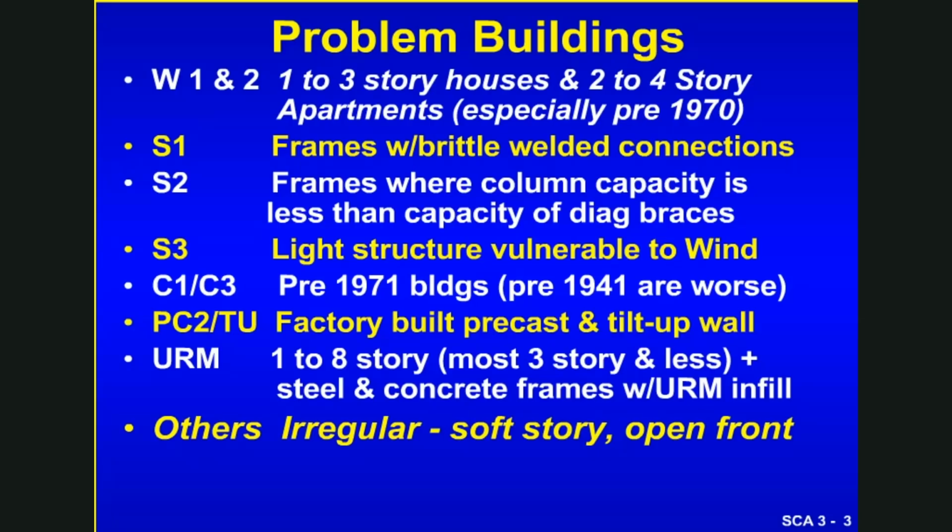Wood buildings, of course, have problems in high winds and also in earthquakes if they're big enough, and steel frames without properly welded connections can be a problem, and certainly concrete frame type buildings have been a problem in Mexico City and other places. And further, historically, the biggest problem has been in unreinforced masonry buildings, since there are so many in the world, in the third world as well as in the U.S., especially in the central U.S. and out of the earthquake regions.